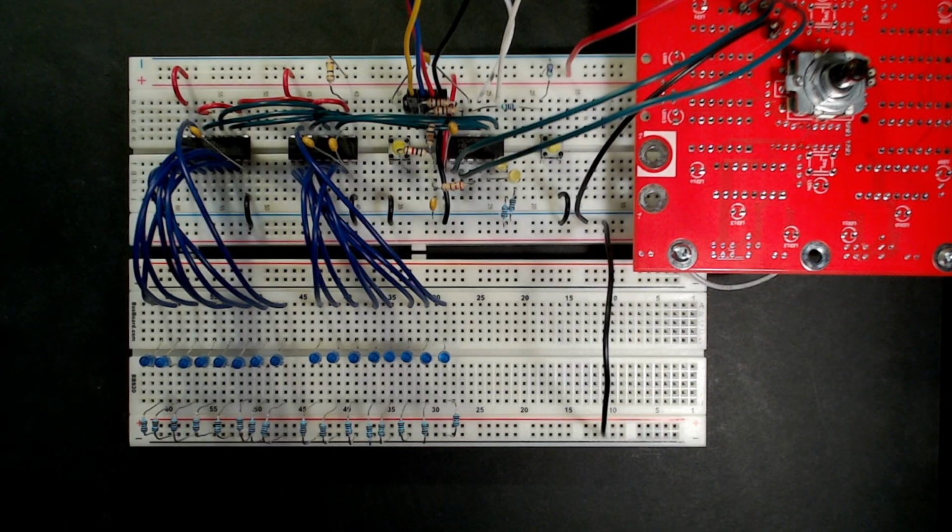Now, as we start it up, no matter how many times we do it, notice all the LEDs are always off. Okay, so that's a step in the right direction. The shift registers are being cleared and reset with every power cycle, but we don't want this to start up with all of the indicators off. We want the rightmost indicator on, which would indicate the lowest intensity level.